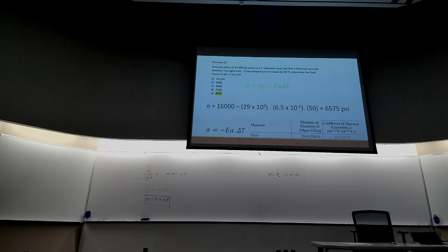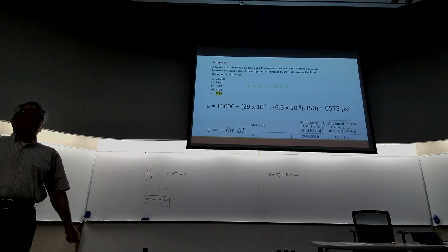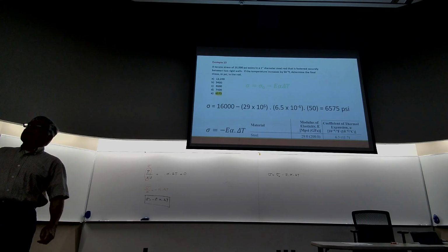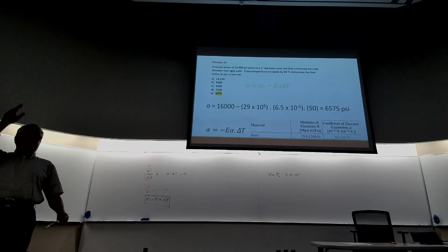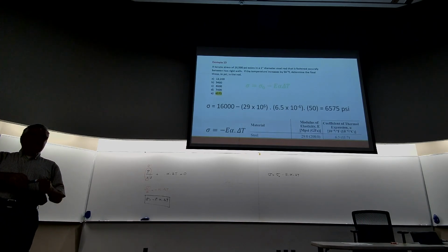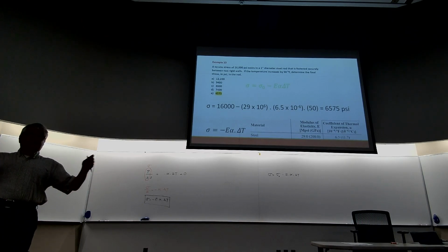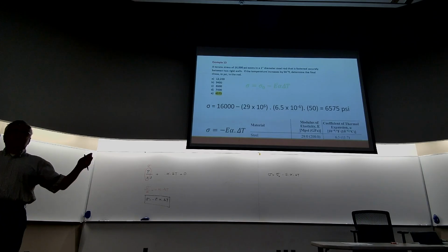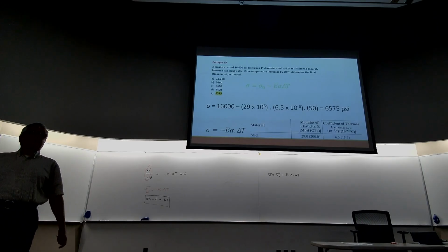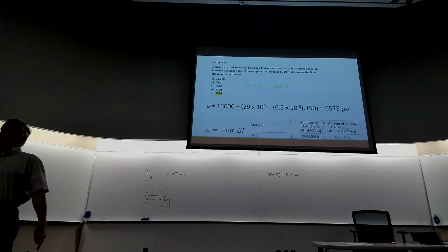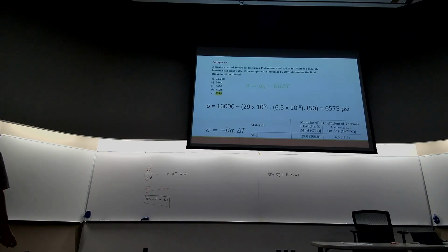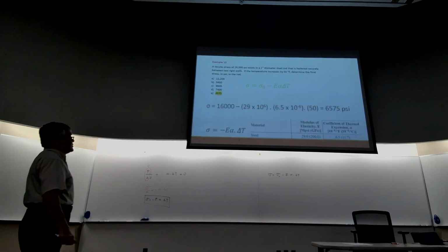If you look at sidewalks, you can see that there are usually square blocks which have gaps in them, right? You don't have one big concrete piece, so the gaps allow the material to freely move. You might have noticed that when you're driving under a bridge, if you look up, the overpass does have a gap in it, right? That's because these beams get longer in the summer and get shorter in winter. So we don't want additional stresses as a result of temperature changes.